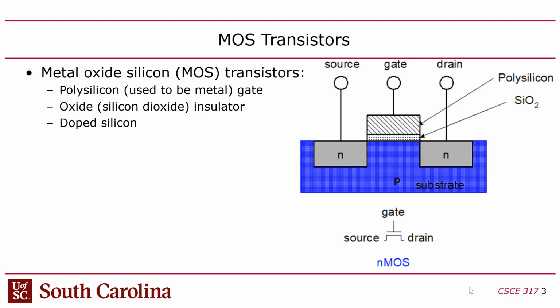Okay, and then you can create islands in there that are of the other type of silicon, the N-type silicon. Now, the way you do that is called diffusion. They have a process where you open up an opening where you want these, called diffusion areas. You open up an area here, and then you use gas. You expose the top of this to gas with whatever N-type dopant you want to put in there, and you make it very high temperature, and those elements penetrate.